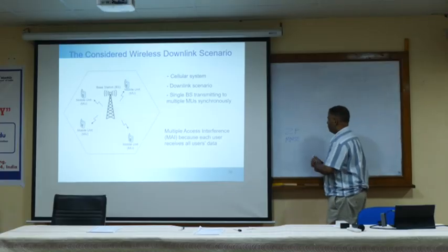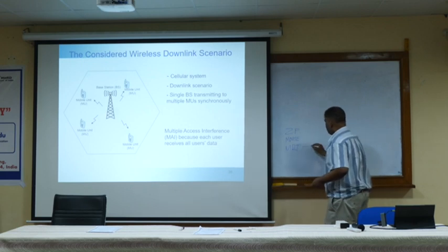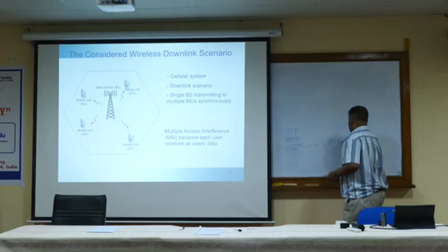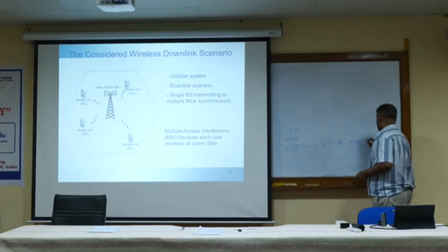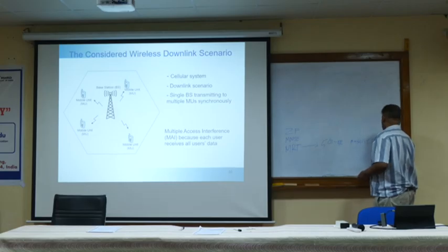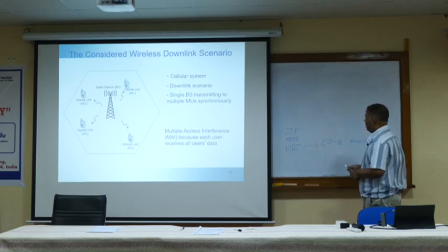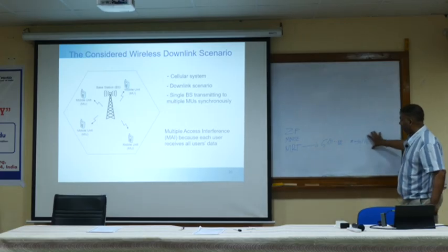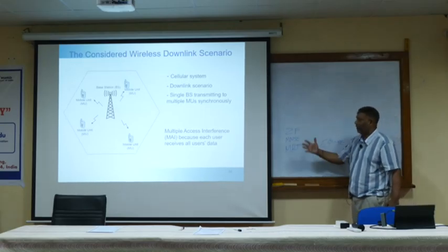And there's another one called MRT, maximum ratio transmission. This is the one happening in 5G NR with the massive MIMO case. This slide set is not for massive MIMO. We will talk about massive MIMO later on. In 5G NR massive MIMO, we only do MRT, maximum ratio transmission is good enough.